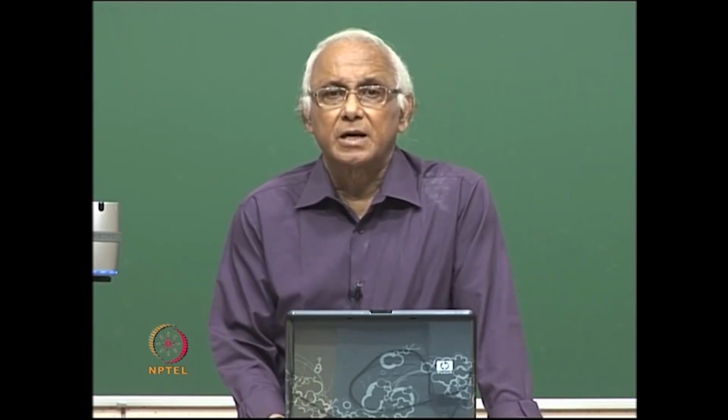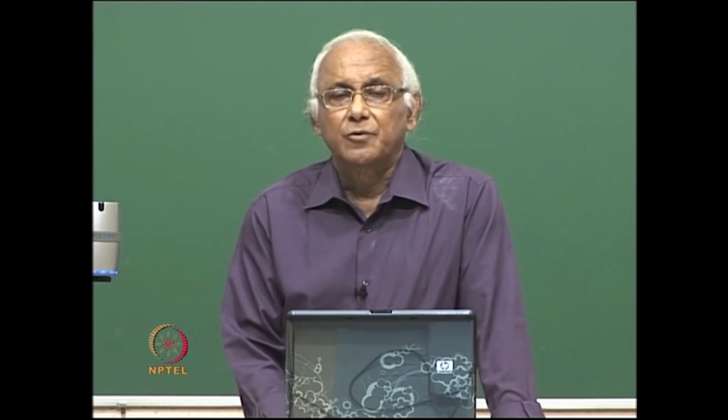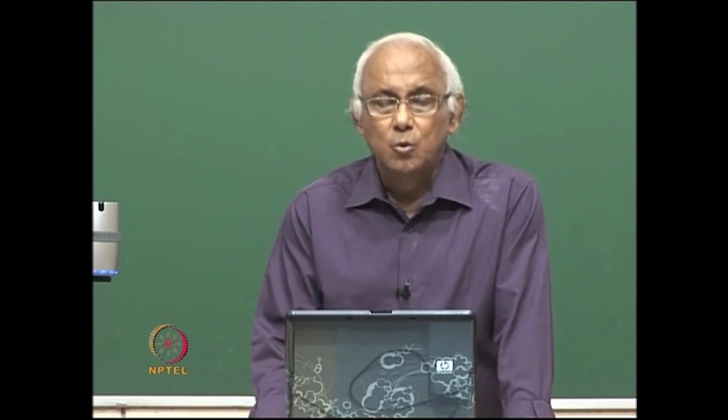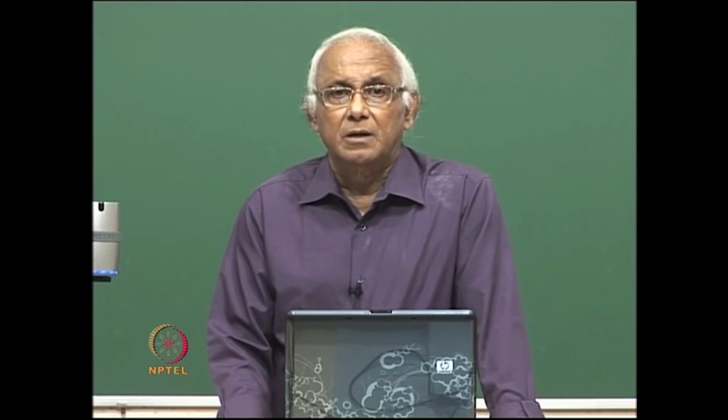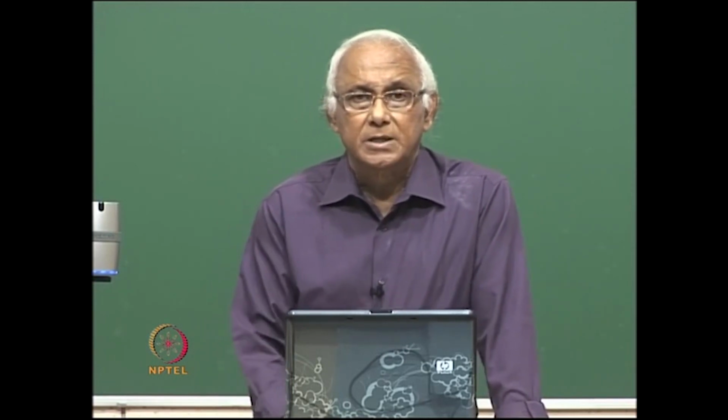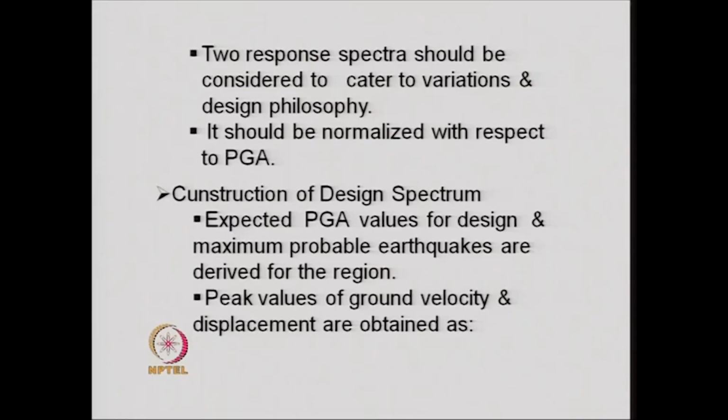So this is the current design philosophy, and therefore we have to have a two-level response spectrum. One is the design response spectrum, the other is the extreme response spectrum.